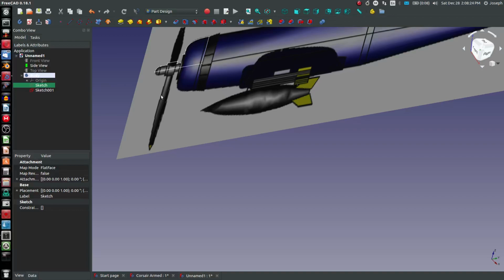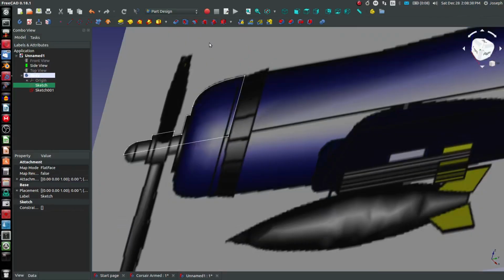if you want to fully constrain, and if you want to scale the pictures right, you can always pull data like what the wingspan would be or what the overall length would be, and create little sketches to scale your pictures to. I like to just make the model and then scale the model when I'm done. I think that's the easiest when dealing with images, but again, you're the engineer, so choose your preference.